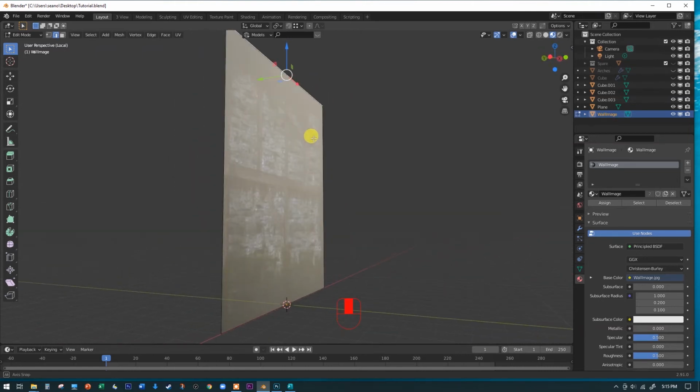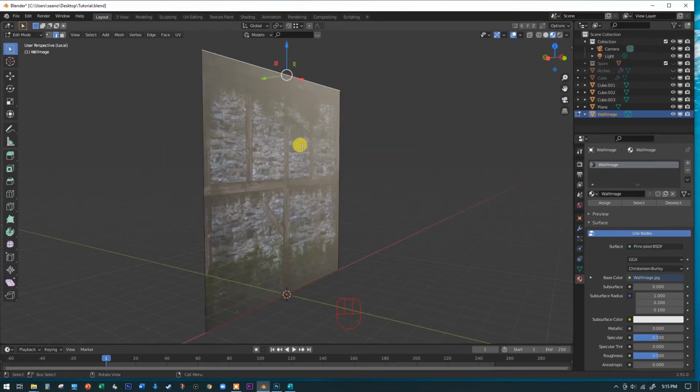It also looks really shiny. Like, what's up? Why is this wall so shiny? Well, those are things that are here by default. Now you can fix these things before you import them, like I talked about a moment ago when we were bringing it in. But we want to find the little beach ball here with the object selected. We want to click on the little beach ball, and we will see that it has a material applied to it automatically, and it's called wall image.